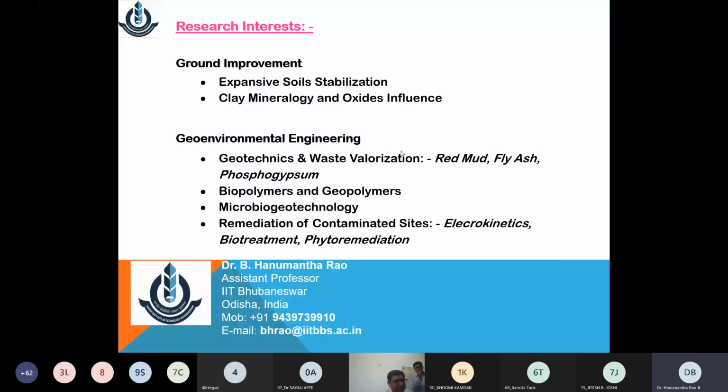One important thing is that when you talk about any waste material, it is certain that it is dominated by a particular oxide or particular mineral. That is how we can distinguish natural geomaterial from waste material. Any material of geological origin maintains some kind of homogeneity. For example, in soil, the oxides composition, that is SiO2, Al2O3, R2O3 and so forth, is more or less uniform. But often there is dominance of particular minerals or chemicals in soils also. To summarize, one has to have a thorough knowledge of oxides and mineral composition.